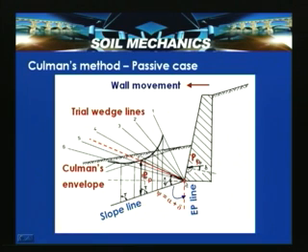So, this is the heel of the wall. From this heel point, with the horizontal at an angle psi, we have drawn a slope line, and from this slope line we have drawn an earth pressure line at psi equal to alpha plus delta. Then we have drawn a number of lines passing through the heel, 1, 2, 3, 4, 5, 6. These are the possible wedge surfaces, because we do not know which one will give the minimum earth pressure thrust on the wall.